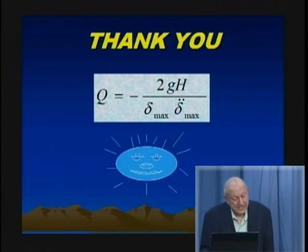And for a single degree of freedom system, we can obtain a nonlinear system with an improvement as high as 2, but an even greater improvement we can obtain when we use something like a box in a box, when we make the system richer in terms of degrees of freedom. I didn't try to evaluate that, but I would guess that we can obtain a significant improvement of the existing cushions if we go in 2 directions simultaneously. We bring in nonlinearities with soft characteristics of the restoring force, and at the same time we design a shock protective system with more than 2 degrees of freedom.